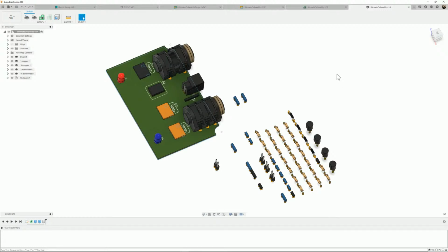They'll just make it solid white or something. But in Fusion, you'll get the translucency, and you can put a chip inside and give it an emissive property in the materials library. You can make it an emitter. Then when you do a render, it actually works as a light source, so you can test your light pipes in the rendering workspace, which is really awesome.